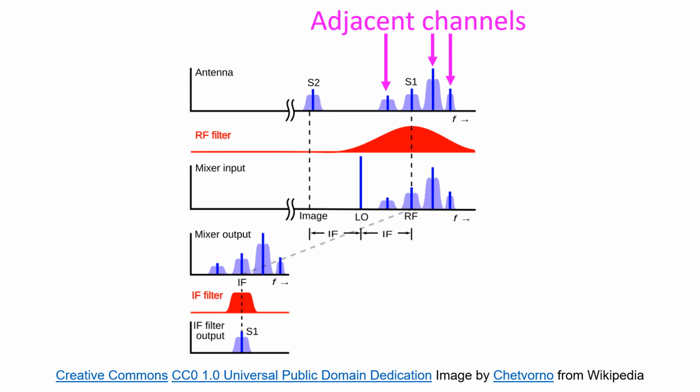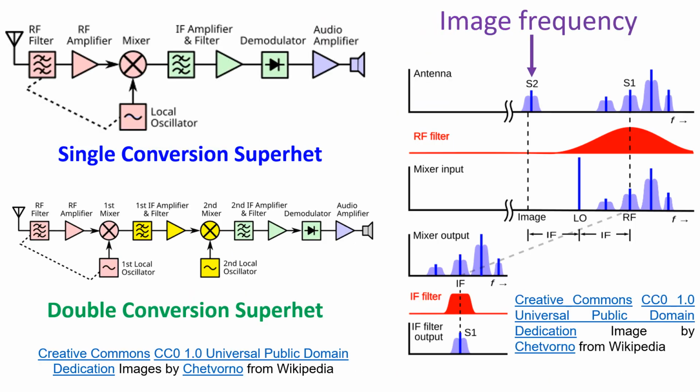In case of broadcast stations, nearby frequencies are not allotted to stations operating in regions where adjacent channel interference is likely. Interference by image frequency is a feature noted in superheterodyne receivers when two station frequencies are separated by exactly twice the intermediate frequency of the radio. Both these signals produce the same intermediate frequency output from the mixer stage.